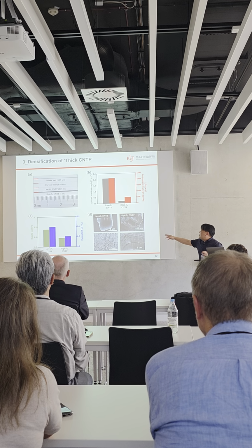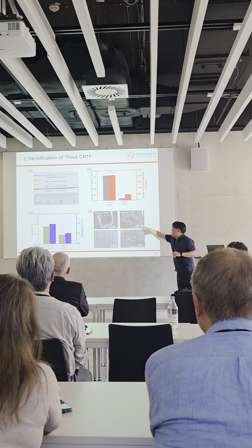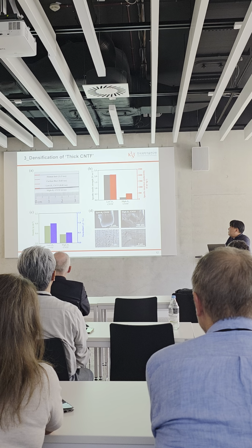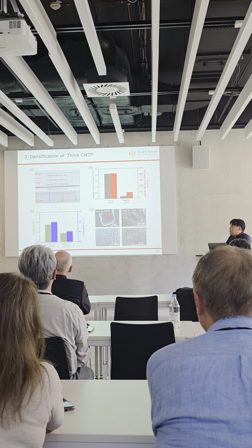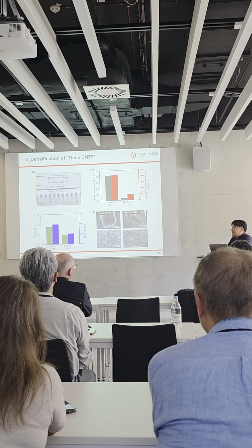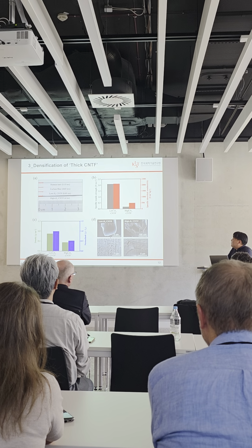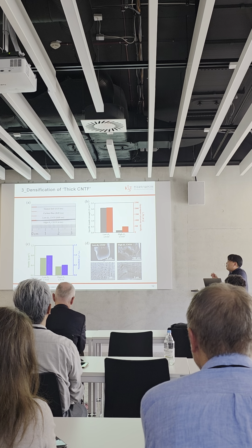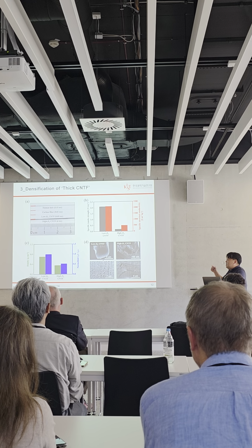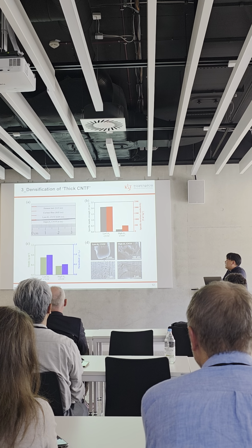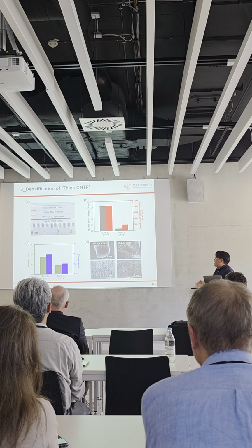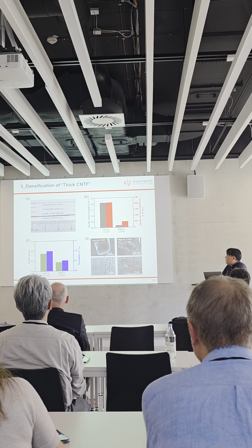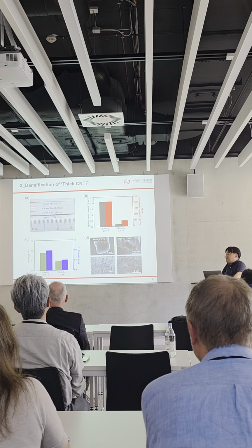You can see the difference in the internal structure at different scales. In the literature, Pasquali wrote a lot about CSA works, and usually CNTs with a high G/D ratio dissolve well in CSA, but the G/D ratio of the high linear density CNT fiber is just about 5 or 10.